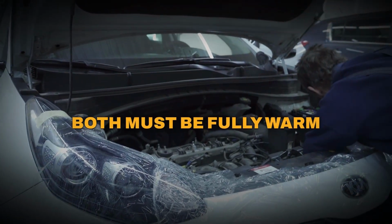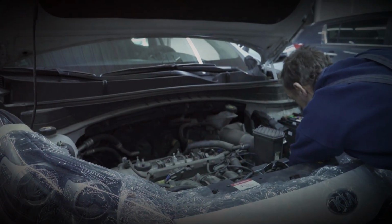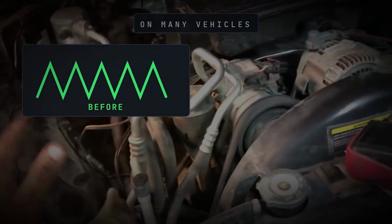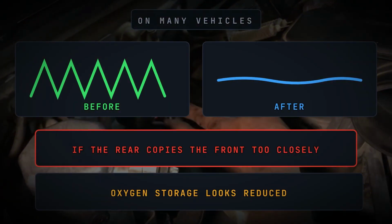When graphing sensor data, the engine and converter must be fully warmed. The vehicle must also be operating under conditions where the catalyst monitor can evaluate the system. On many applications, a healthy converter reduces the rapid oxygen changes seen before the converter. The downstream signal, therefore, behaves differently from the upstream signal.